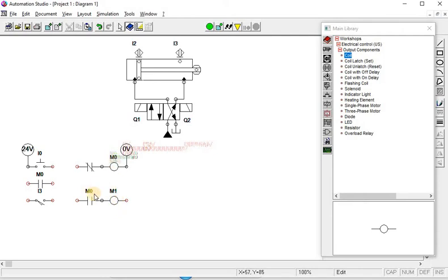So you see, the step marker is used to follow the sequence we have assigned. We won't like it if M1 is energized but M0 is not energized yet, right? So it should start energizing from 0 and then 1. I hope you get my point here.